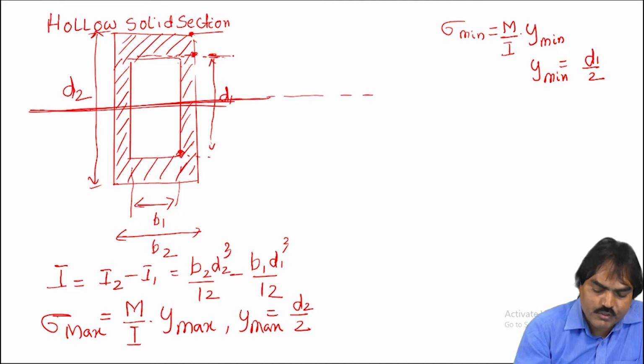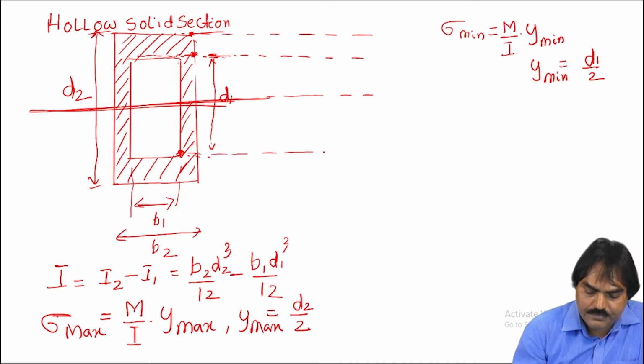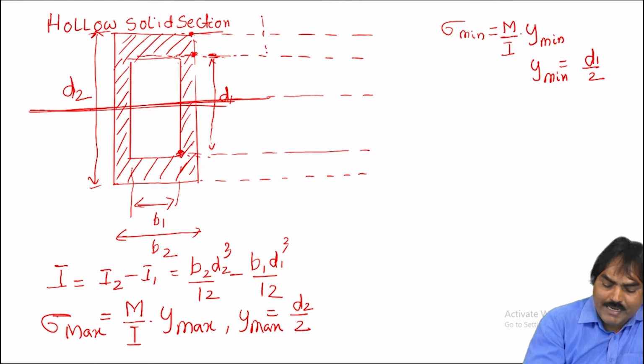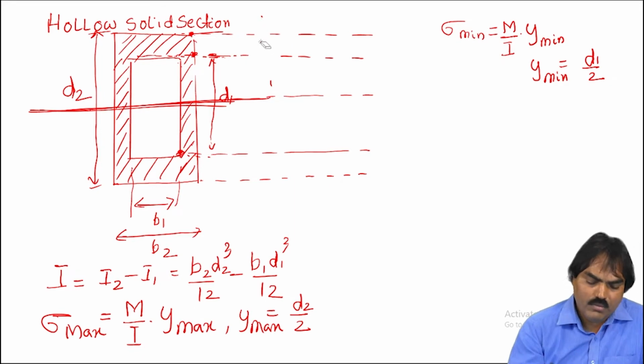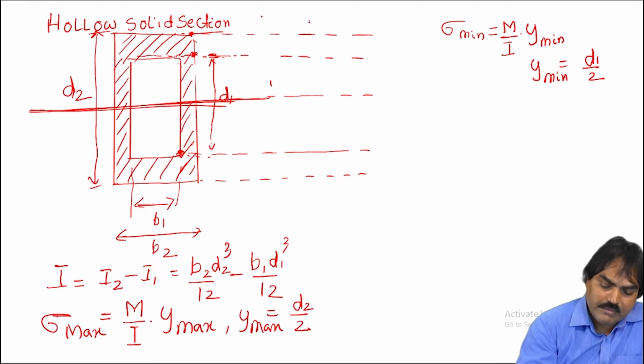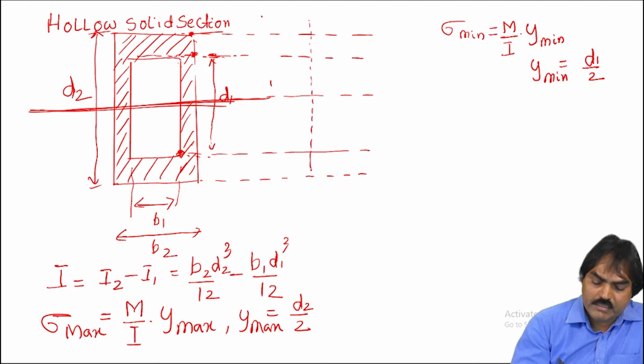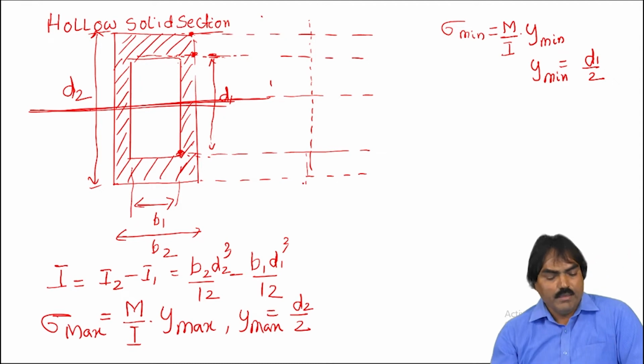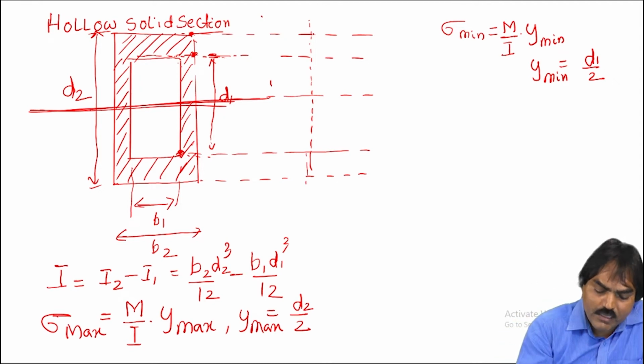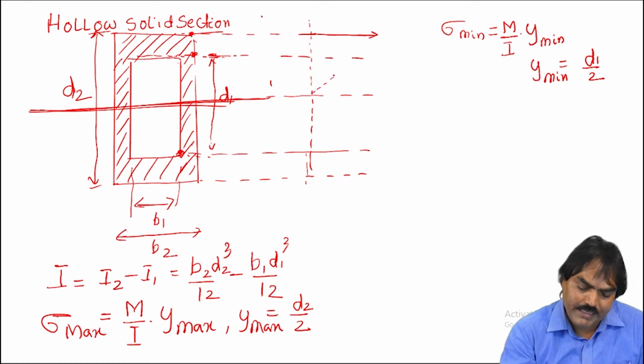So to draw the stress distribution, let us extend the lines. These are the construction lines. Now draw the reference line. Draw the reference line somewhere here. This is the reference line. See, top tension. This is the tensile stress. And it will vary linearly.